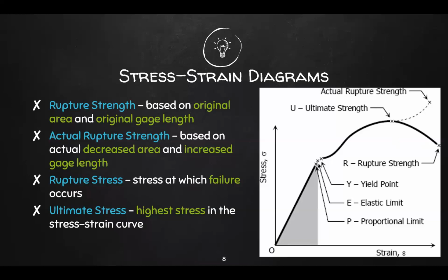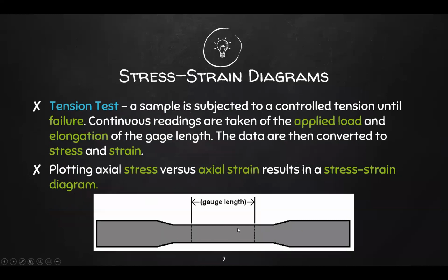So beyond tensile strength, a neck forms where the local cross-sectional area becomes significantly smaller than the average. So to give you a visualization, let's say this is a rod of uniform cross-sectional area. Necking occurs when the cross-section of this suddenly becomes significantly smaller. So something like this. Hence a neck, right? Something that suddenly thins out. That's why it's called the necking region.